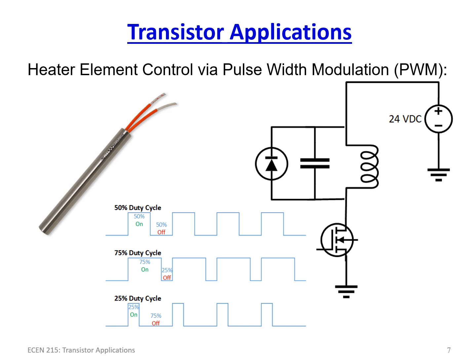And again, if you notice, the overall control circuit for the element is the exact same circuit we were just looking at a moment ago. The only thing different here is this digital waveform is now a square wave at some frequency, and we're controlling the on time. The good thing is that modern microcontrollers, for the last 20 years or so, usually have various peripherals, and some are specifically designed solely to do this, having multiple channels that do nothing but provide PWM signals.